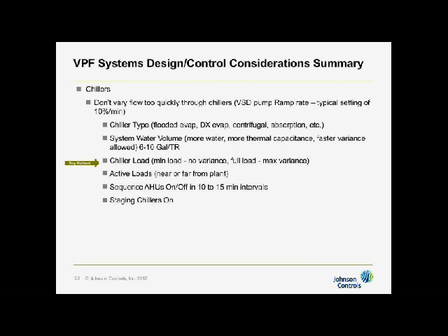Chiller's load changes what the rate of change is. If the chiller is fully loaded, it can handle its maximum change, whatever that might be. If in a given system 20% happens to be maximum, then it could handle 20% at 100% load, but when you're down at 10% load or min load, it'll literally shut off if you lower flow. There's no place for the vanes to go. They're fully closed. They can't close anymore.